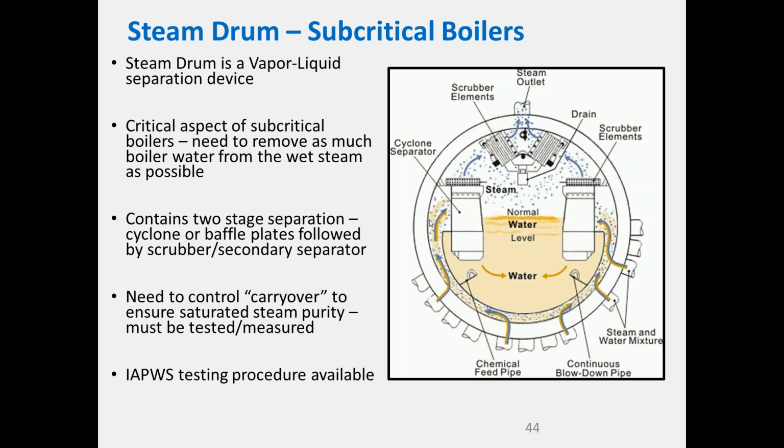If you can imagine it, say the operator gets the drum level control wrong and that drum level comes up and it actually touches the scrubbers, then we'll get water getting sucked through. Or if these haven't been attached properly into the boiler, or there's a hole or something like that, then you're going to get suboptimal steam chemistry coming out the other side.